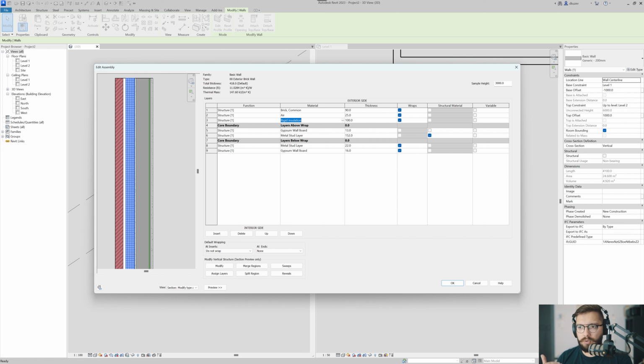So in general, you want to be able to create all of these materials so that you can use Revit to the fullest extent, okay? And the last thing we need to take care of is all the layering here. So we can agree, hopefully, that that metal stud layer, it's a structure. I hope that we can agree that this gypsum wall board is not a structure, but it's a substrate because I will use it to attach my insulation onto it.